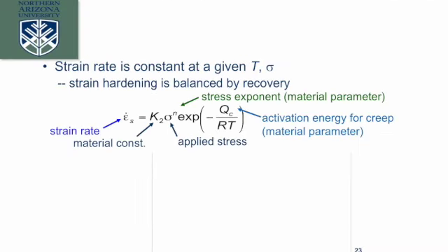All right, so how do we do that? Well, it follows the same rule we've seen so far. We have a constant energy, kind of a toughness of a material that's known for the material. That's our K value. We have the strain rate, which is the rate it's deforming over time, and we have our exponential equation. We have our initial stress, an activation energy for creep, which is the resistance of the material to creep, our gas constant, and our temperature. It's the same exact equation we use for diffusion, and for vacancies and atoms in crystals. This also helps us determine the strain rate.